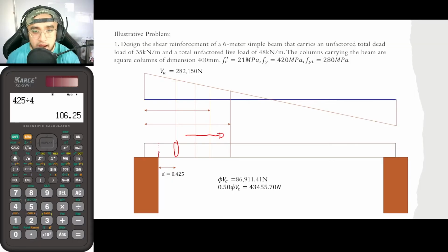As you can see here, for our shear, as it goes to the midspan, it actually decreases up until 0. So making use of 70 mm spacing at this region is uneconomical because we do not really need that much spacing.